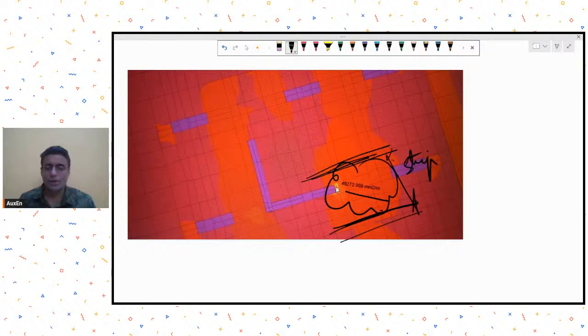So you can accordingly decide the width of this strip. Once you decide this width, you can construct that strip, and then SAFE will give you a value of Ast for this entire strip width, and here it will do the averaging on its own.